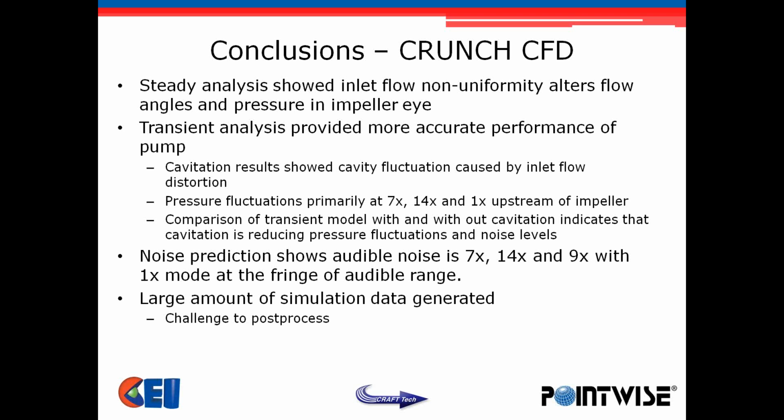We were able to analyze the pressure fluctuations primarily at the diffuser, the impeller blade frequency along with its harmonic. And we also looked at comparisons of the transient model with and without cavitation.